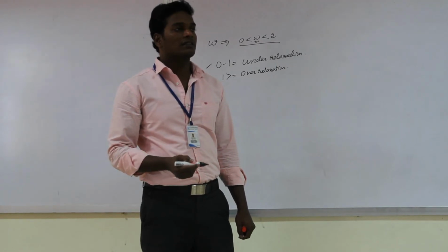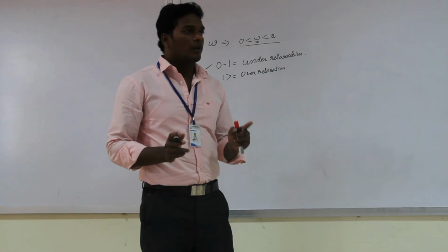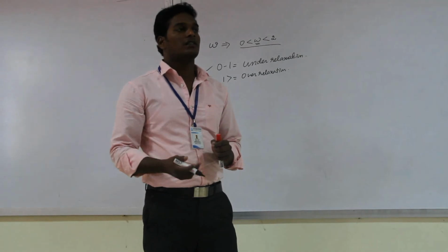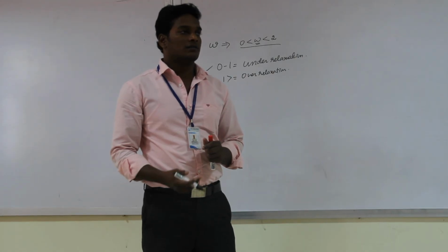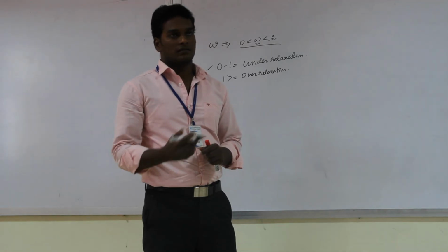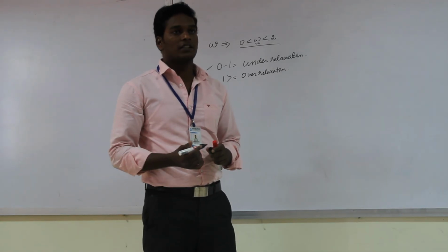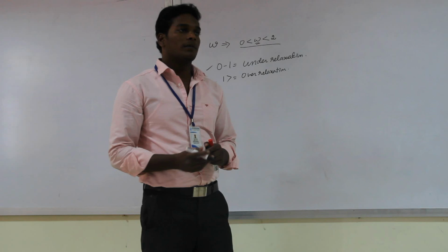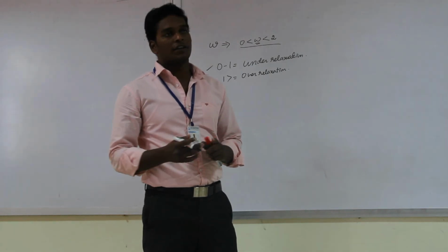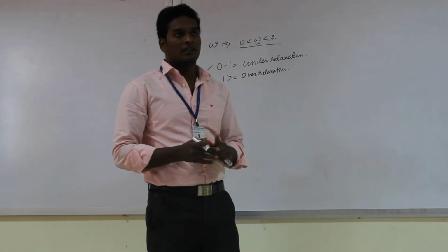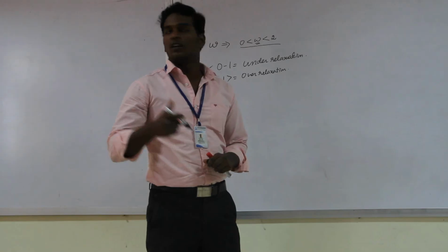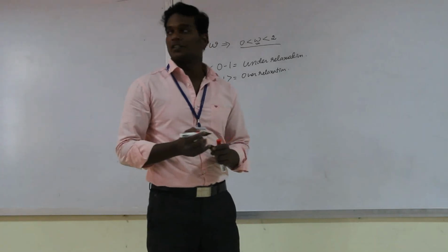So for the relaxation value you have to give within 0 to 1. It will give us an easier solution and it comes faster. Our solution result comes faster than with over relaxation. The under relaxation limit varies with respect to our problem, and when you give under relaxation, there is a coupling between time, iteration and technique. So we will see this in a graphical representation now.